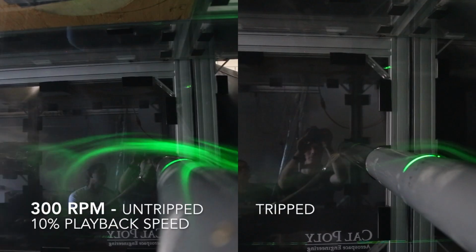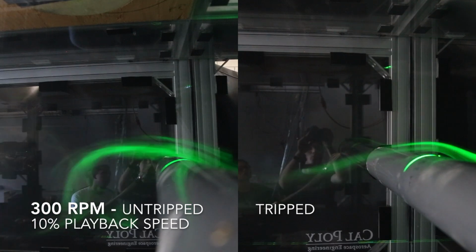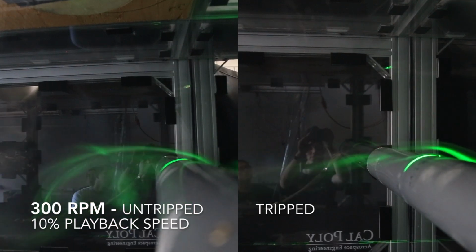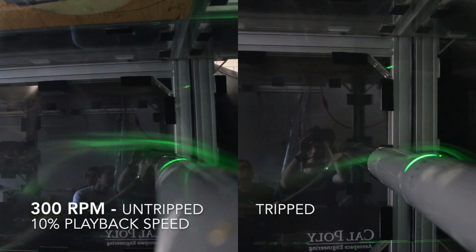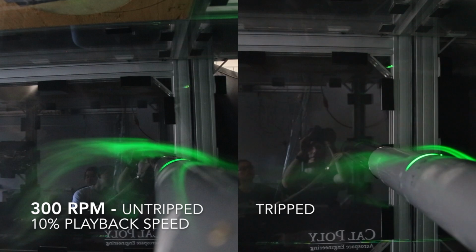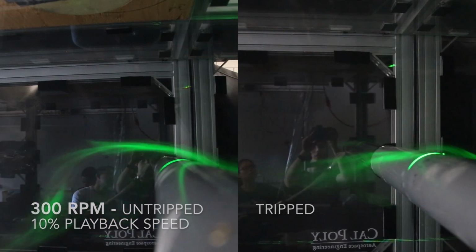These poor conditions were caused by the large amount of light in the room and the lack of smoke because the smoke machine was malfunctioning at the time of testing. Because it was difficult to observe the frequency at which the vortices were shed, an attempt to calculate the Strouhal number for speeds greater than 5 meters per second was not taken.